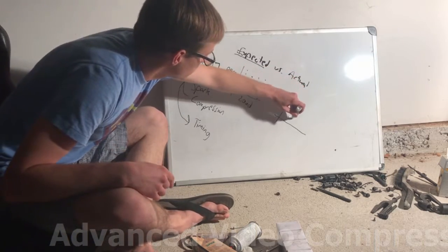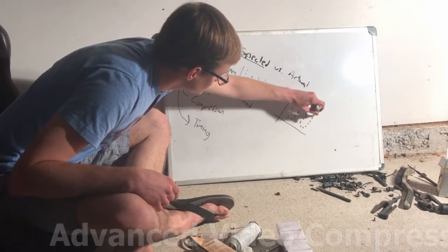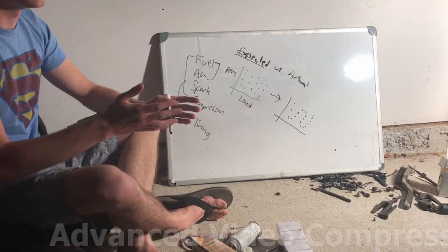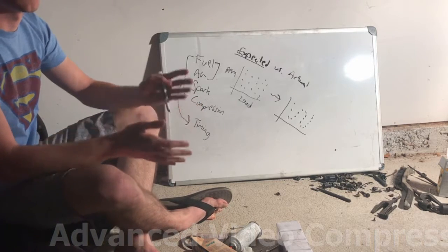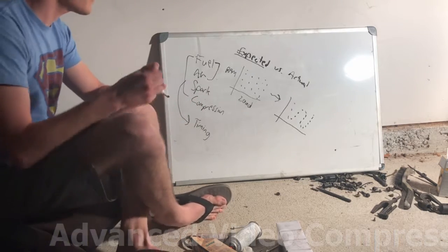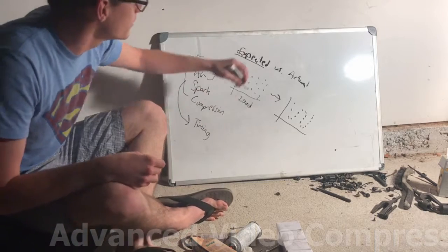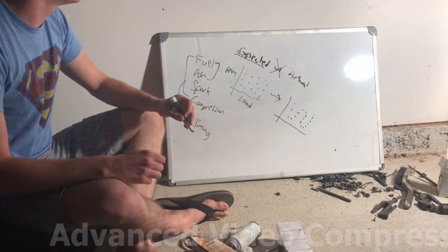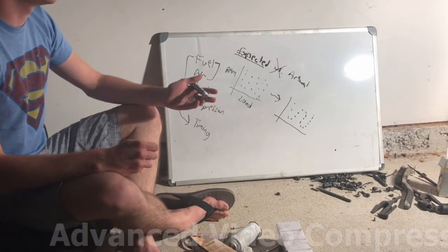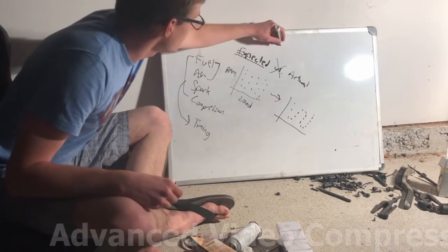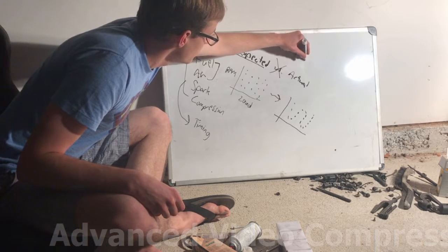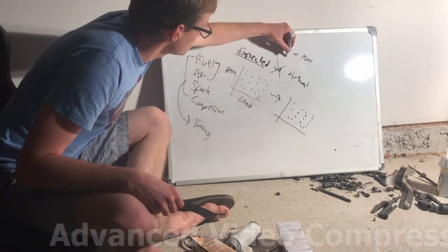So there are going to be slight differences in these values, and they're not going to match. But there's a window in which these values are supposed to be pretty close to each other, right? And if it falls outside of that window and expected does not equal actual, then the car will throw a check engine light for either the MAP or the MAF sensor.